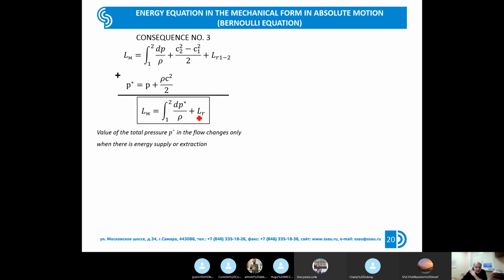And the second difference: in the equation for the total pressure, we have losses. Of course, losses have influence on the energy equation in heat form, but the heat of the losses is allocated inside your system, and that's why total enthalpy and total temperature will not change. In the case of the total pressure, losses will have influence on the total pressure.